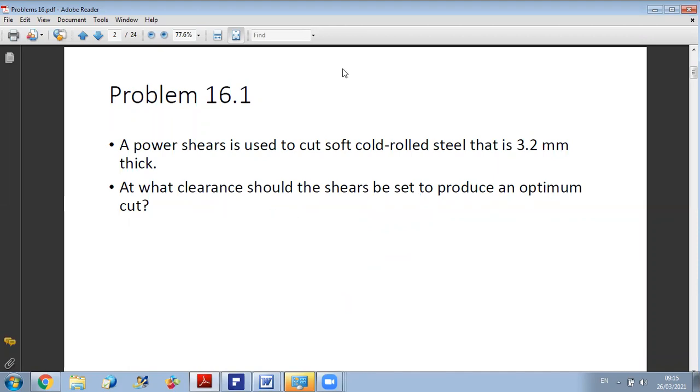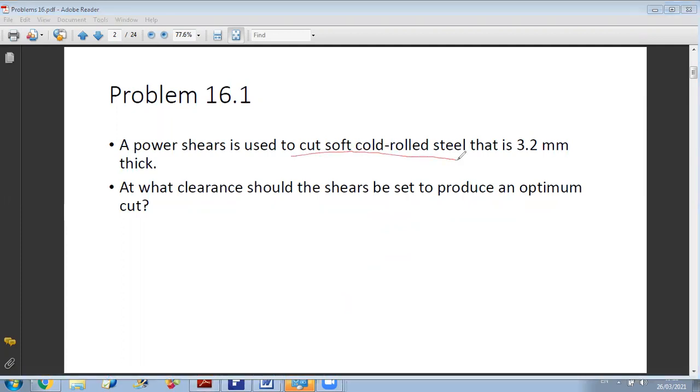So here you have first the type of material used. This will give you the clearance allowance, AC, and you have the thickness of your stock, T. This information will help you to get the clearance. So AC times T is equal to the clearance. This is just a direct application to know how to calculate the clearance in a shearing operation.